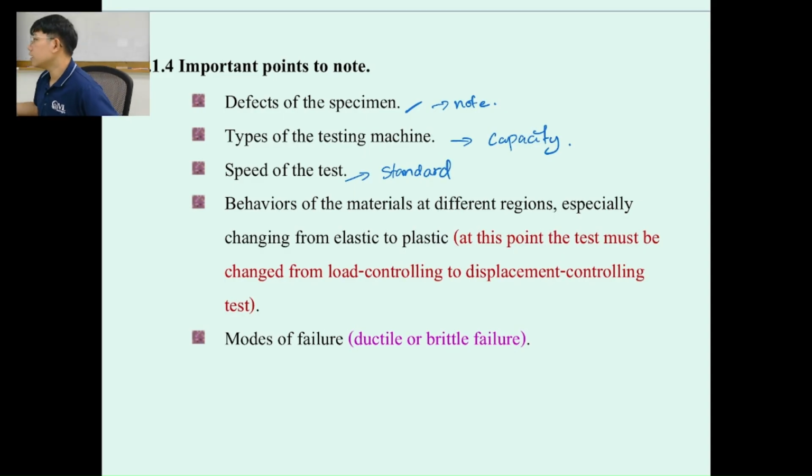Right now we use the machine in order to get a constant standard. But for our lab, Ajahn Sitichai would like you to feel the test by yourself. So that's why we still have the manual machine. But that manual machine is going to produce a lot of error. Because one sample you're going to apply really slowly and another one really fast. So the speed of the test matters to the testing results.